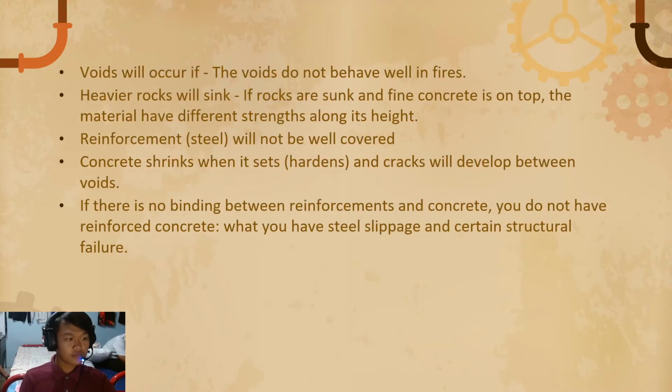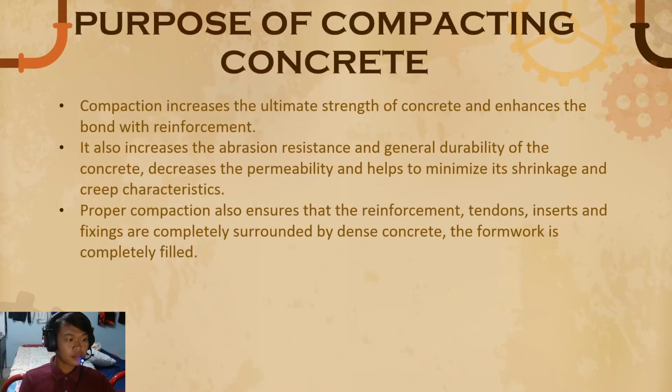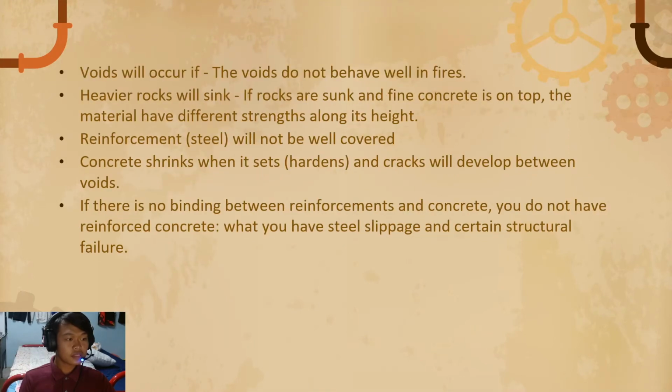Point 4, voids will occur, and voids do not behave well in fire. Point 5, heavier rocks will sink. If rocks sink and fine concrete is on top, the material has different strength along its height.